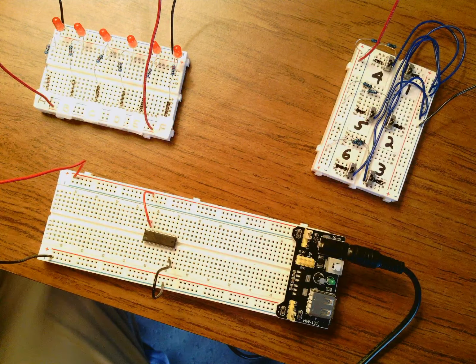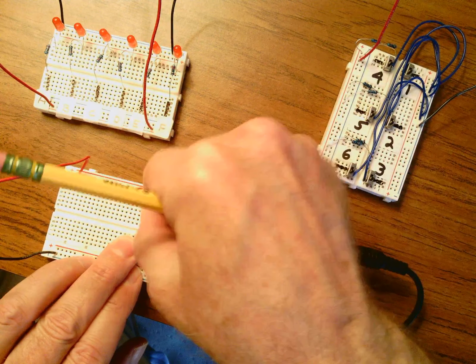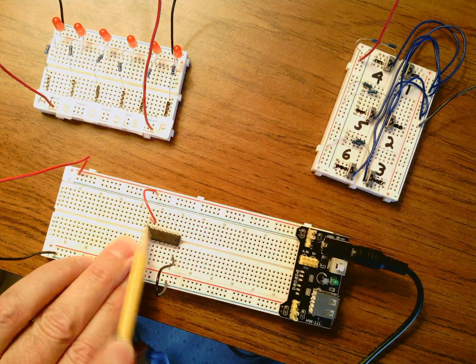I want you to get in the habit of doing that, because when you have trouble with your labs, it'll be very easy to troubleshoot. A lot of students will end up missing this by one. This is hard to see, and they won't bias this up, and their circuit's not going to work. You have to look these over very carefully and make sure that you're going to the correct pin on that IC. If I had a face-to-face class with you, I'd be able to take a look at this real quick and see if these are biased correctly.